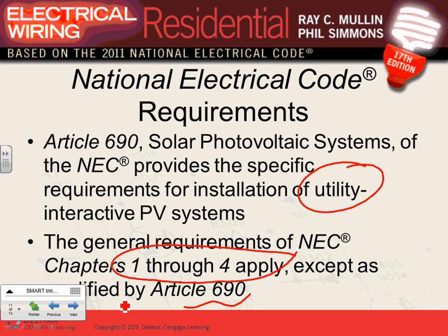An interactive system has no batteries, guys. An interactive system with a battery backup, a battery is an addition to it. You can add batteries. You can charge these batteries. If you lose the power, the interactive system isolates you from the grid first, and then dumps the power directly into selected loads, a selected group of loads.